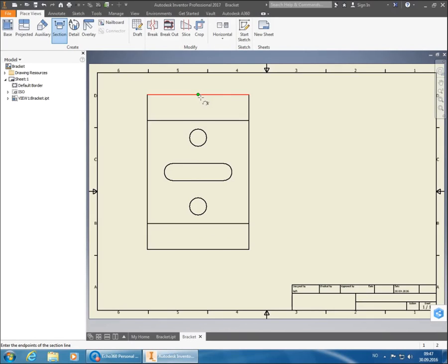You can go into each of the dimensions, and you can write the number in millimeters, and then actually press millimeter behind. So you can put two lowercase m's behind the dimension. It's going to put it in millimeters. But the problem is, as soon as you're trying to do your drawing, it's going to give out the dimensions in inches. Yeah, so you can work around it in your 3D parts by telling it to use millimeters instead of inches. But as soon as you go into your dimensions to place in the drawing, it's going to show you in inches. So I'm not quite sure if you can work around it in the drawing.